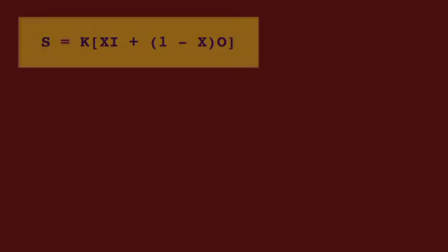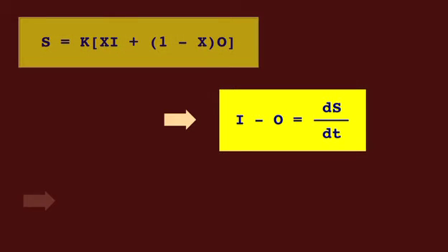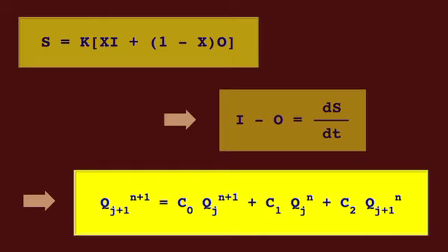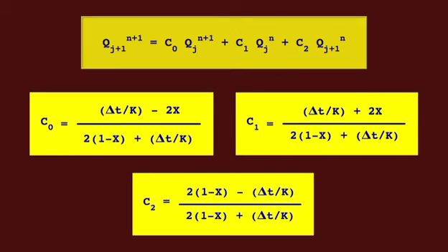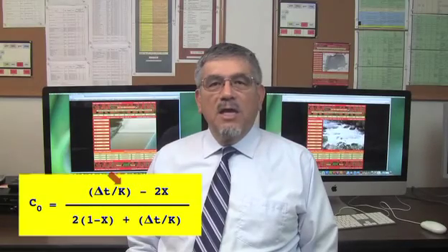The substitution of the Muskingum relation into the differential equation of storage leads to the routing equation, with the routing coefficients. The parameters K and X are obtained by calibration using measured data, that is, with stream gauging. Therefore, the method is strictly applicable to gauged streams.